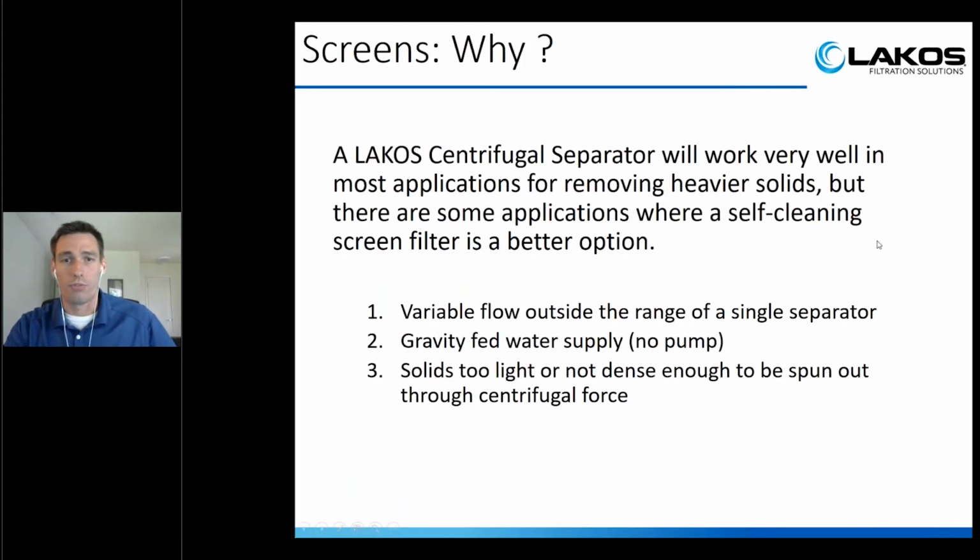So why would you offer a screen filter? Our separators are kind of our workhorse. They've been known to satisfy most of the application requirements for filtration. They're great at taking out the heavier particles, the solids, the sand, silt, pipe scale, rust. But sometimes a screen filter is a good supplemental or standalone filter, depending on what's in the water and what your downstream filtration requirements are.